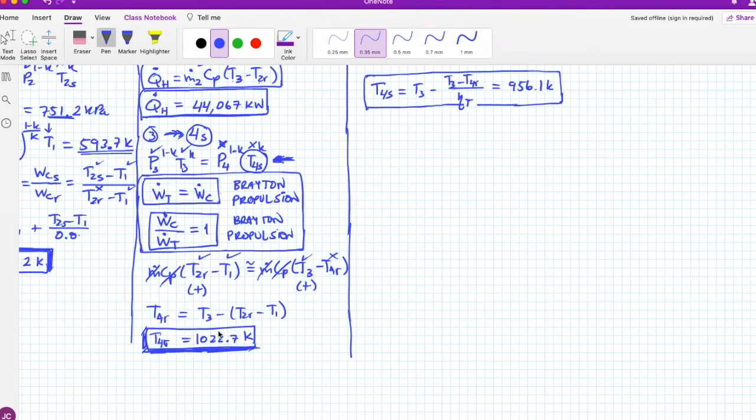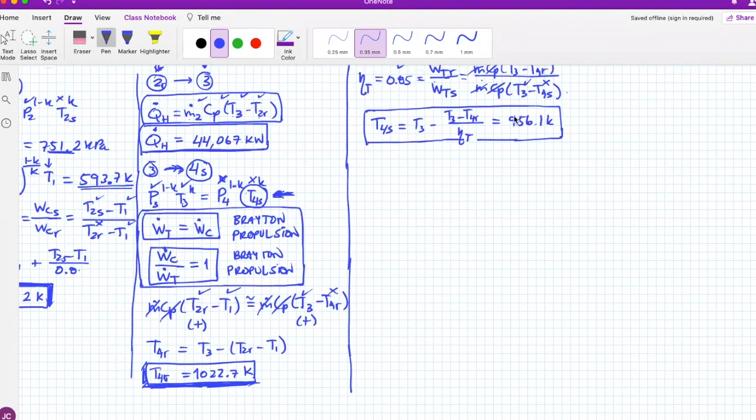than the temperature at the outlet of a real turbine. So that means that the real turbine couldn't possibly take all the thermal juice out of the incoming mixture of air and fuel at 3. But the ideal turbine would. That's why it has an efficiency of 1, the ideal one. So that's why you have a colder temperature at the outlet of this turbine.